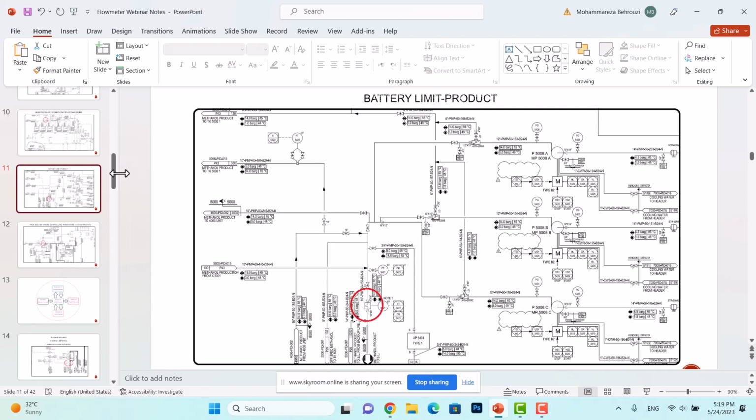We have other fluids which enter or go out of the plant at the battery limits. For those fluids which are not categorized as products, we can use vortex flow meters as well, depending on its status, whether it is clean or not. But it is always better to use Coriolis flow meters even for those fluids which are not products, because you are dealing with money.